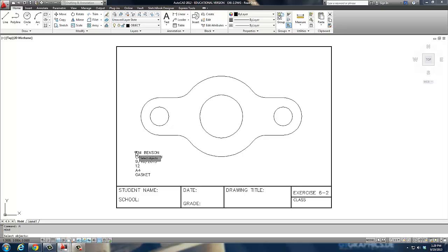and then all I have to do is go use the move command, which is M, and I can move these right to where I want them to be. Turn off my ortho lock so I can set them right where they need to be. That really and truly is all it takes. Thank you for your time.